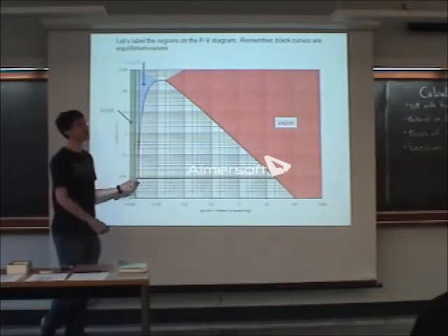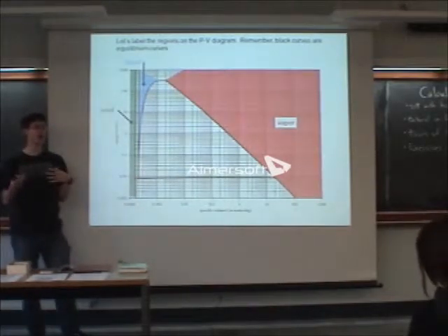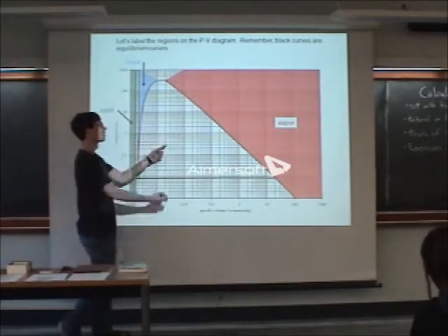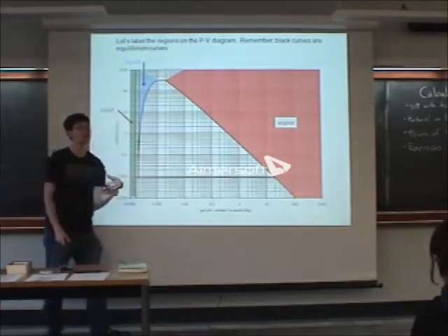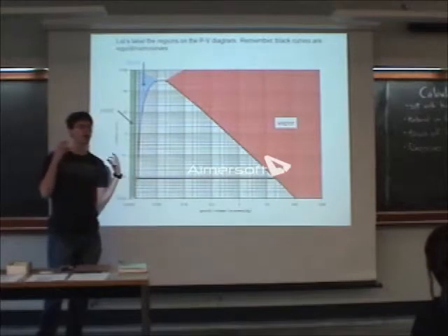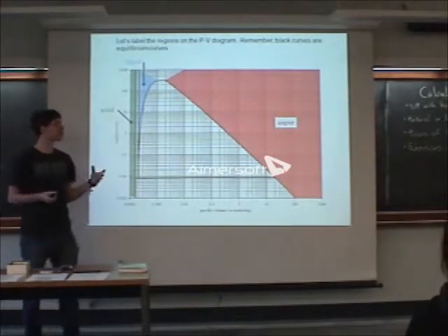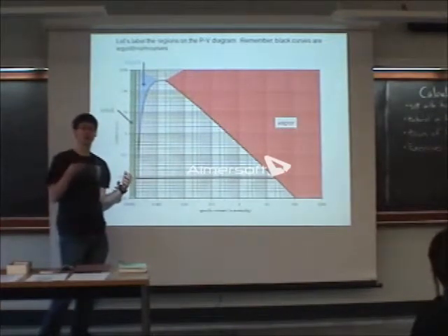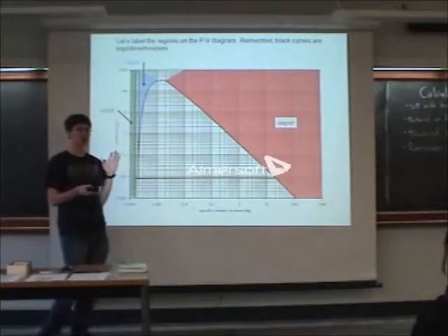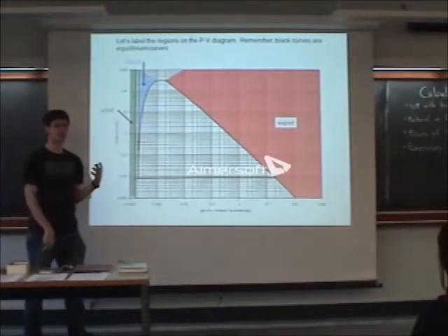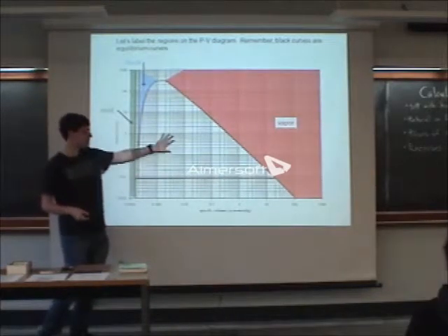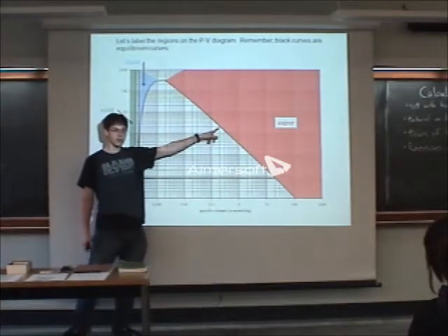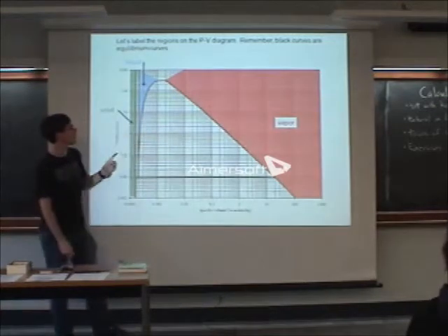Yeah. So just like on phase diagrams before, where we've had a 2-phase region and it can split up, that's exactly what's going on here. If you put a point here at 1 atmosphere, it's going to split up into your 2 phases. On the diagram we were just dealing with, these regions were represented by a single line. The liquid vapor region was just a single line going down the graph. And if you were moving across that line, you weren't actually moving anywhere on the temperature pressure graph, but you could still be moving around in that 2-phase region. We can see that here, and that's because when you're dealing with volume, when you're compressing, vapor has a much larger volume than liquid. So it's something you can actually see on this graph.